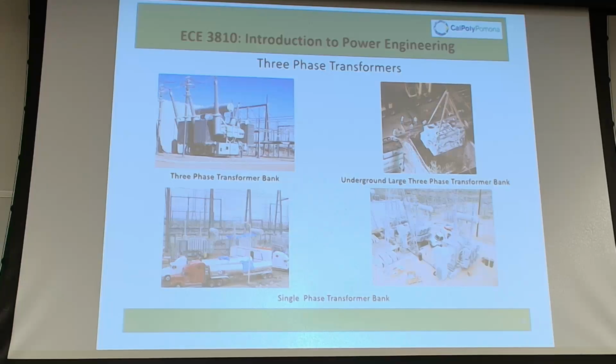If you bring them too close together, you're going to have flashover, right? So there's a minimum clearance that you have to keep between phases, between the two potentials, without ionizing the air and having a flashover between phases. But remember, there are two different potentials. If it's a 500 kV, it's 500 kV line-to-line RMS.